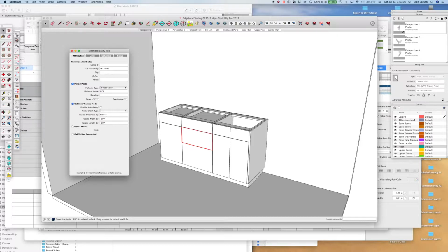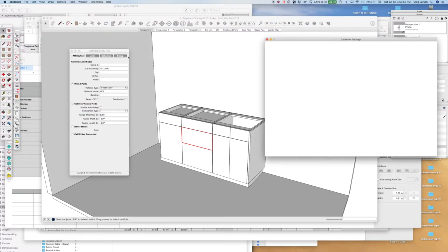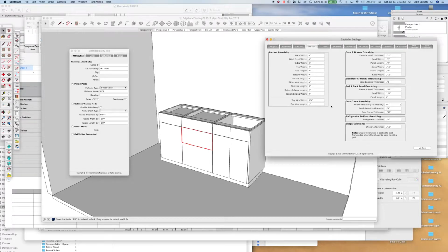So in this case, we've resized the width and the length of this part each by 1/4 of an inch, which makes sense because we had our edge banding set to 1/8 of an inch, so 1/8 on top and bottom is 1/4, a negative 1/4. Because we want to make the part smaller, and same with the width. Now I also have the thickness being resized by 1/16 of an inch. That is right here.